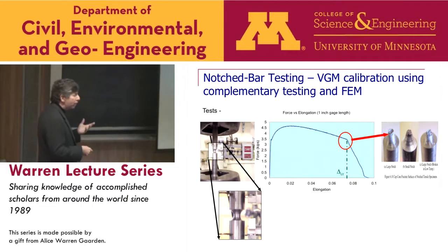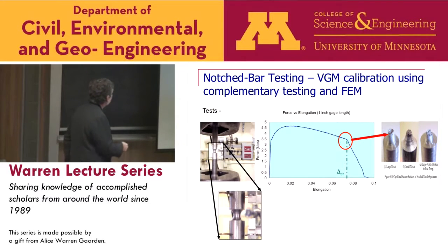And so, ways we evaluate this, and where you could see it, is if you look at a tension test here. These happen to be bars that we put smooth notches in, but it could actually be a normal tension coupon where they neck down and form their own notch, if you will. You load those up, we start to get localized necking happening, it goes out here, and then suddenly it fractures and drops off rather quickly.